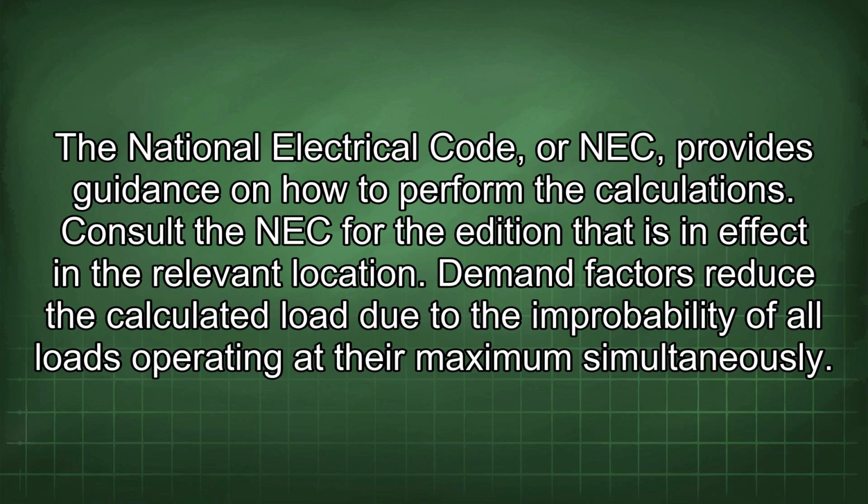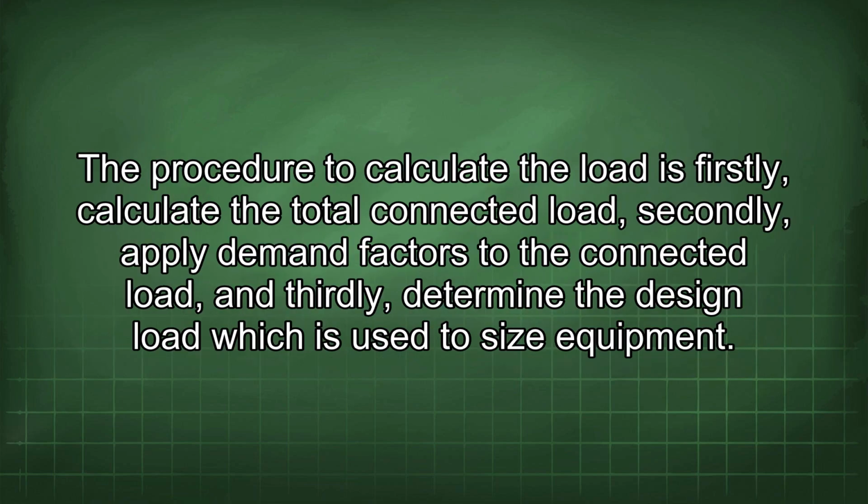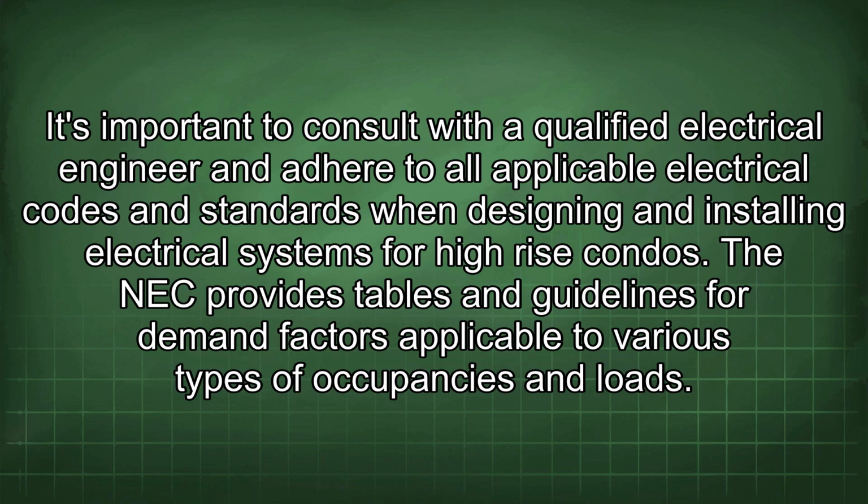Demand factors reduce the calculated load due to the improbability of all loads operating at the maximum simultaneously. The procedure to calculate the load is: firstly, calculate the total connected load. Secondly, apply demand factors to the connected load. And thirdly, determine the design load which is used to size equipment. It's important to consult with a qualified electrical engineer and adhere to all applicable electrical codes and standards when designing and installing electrical systems for high-rise condos.